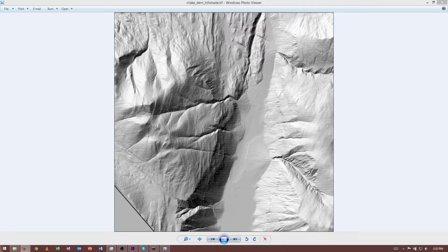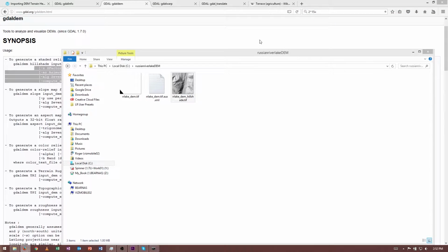This is important because if we have a lot of vertical elevation, say 1,300 meters like we have in this map, and we can only have 256 distinct levels, that means that each level is separated by 5 meters, and if we process it to only have 8-bit resolution, which by the way is what you get if you use ArcMap. There might be a better way to get ArcMap to spit out a 16-bit file, but I haven't figured out how to do that, and I wouldn't claim to be an ArcMap expert.